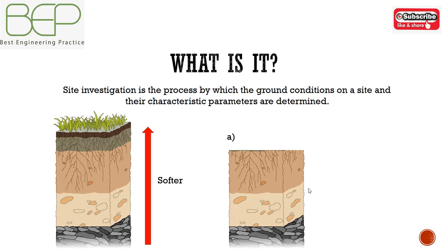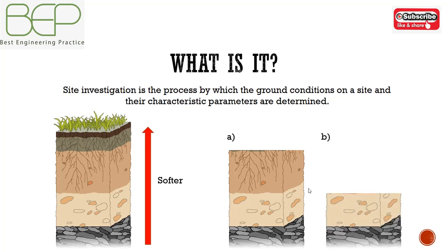In the first case, the structure might have to sustain lateral earth pressures close to those in situ existing before construction, or more likely, if the wall was allowed to yield away from the soil, sufficient active earth pressure, which would be determined from in situ soil properties. In the other case, he might excavate the soil adjacent to the structure and replace it after construction. Then compaction methods will largely control the final pressure.